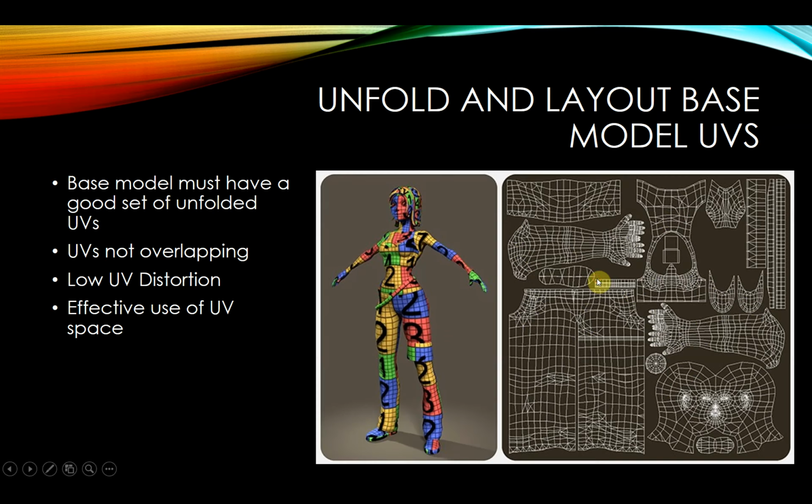Okay, next. Okay, UVs. So your UVs need to be nice and clean. I think we've talked about clean UVs in the past. The main thing I want to highlight here is, again, no overlapping UVs. So for example, if we had this hand here, in some workflows you might want the UVs here to be laid exactly over the top of this hand here. Okay, it just makes it more efficient when you're painting it. It makes more efficient use of textures. So there's certain workflows where you might want to use that.